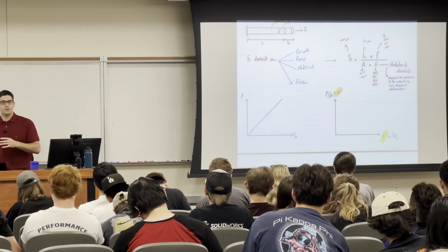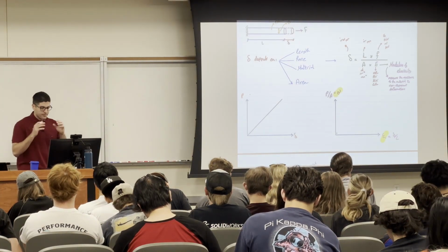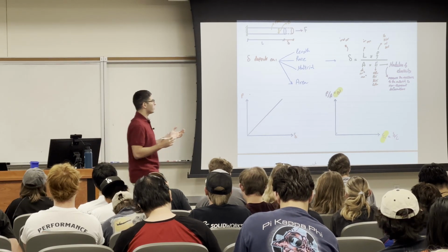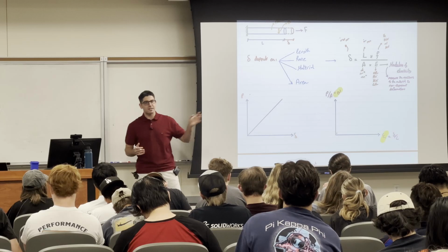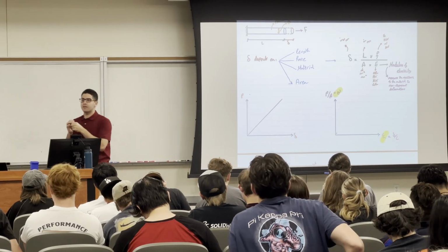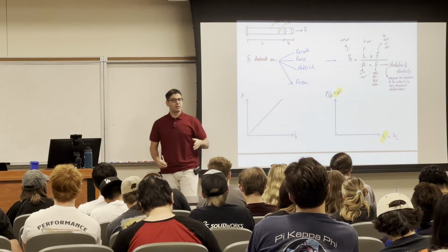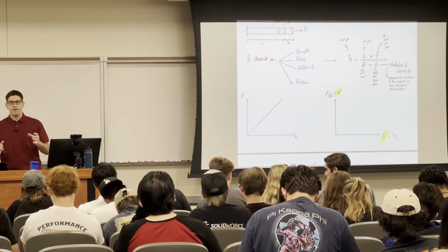So you have a lot of things missing that can't build your judgment. That's why we need to make this curve more meaningful. So we divide the force by area to have it in stress so that we know what the unit area feels. And then we divide this delta by L to know how much deformation per unit length. So now we have everything.